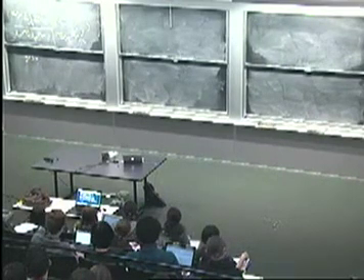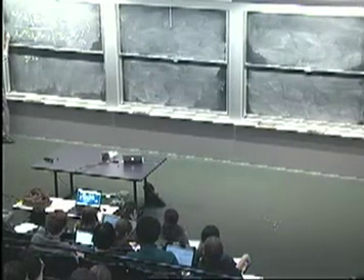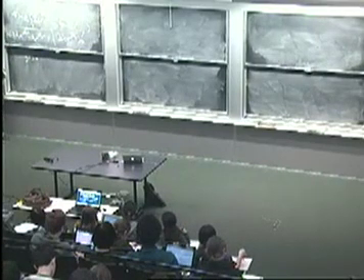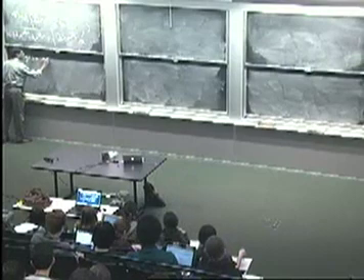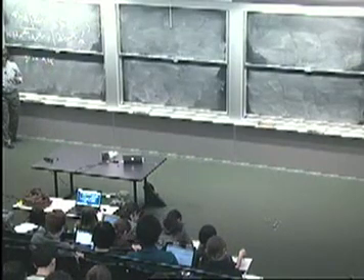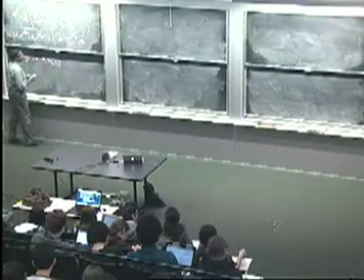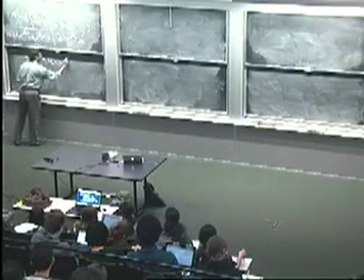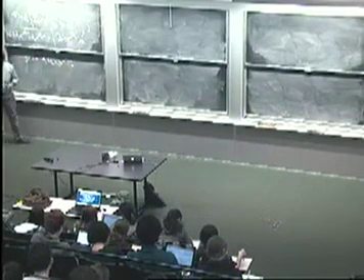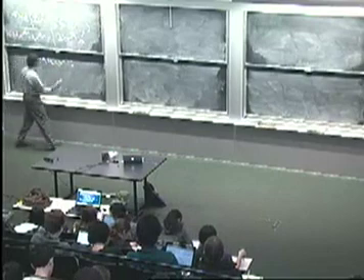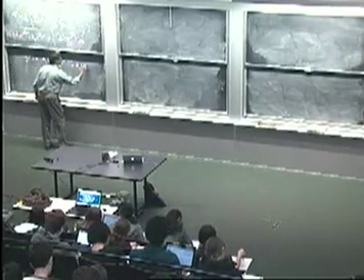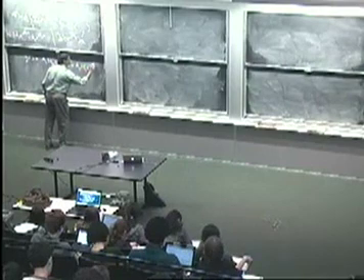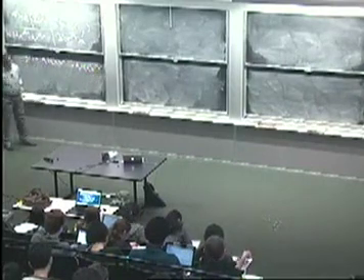So can you tell me explicitly what I would get in this case? If this was x of n, then y of n would be a1 H. Is it just omega? Omega 1, right? It's the frequency response evaluated at the frequency that you're interested in, and then e to the j omega 1 n. And then the response to the other term, right? This is what superposition is about. Okay, so that wasn't so hard.